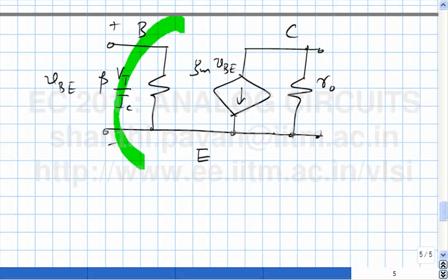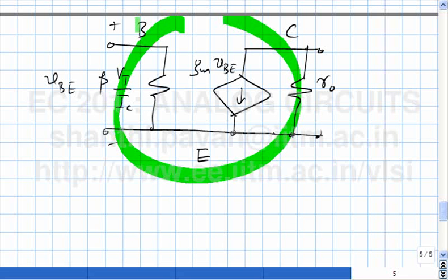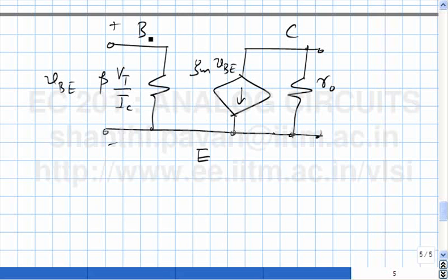The VCCS is not as ideal a VCCS as you want, because what is the input impedance of an ideal voltage controlled current source? Infinity. Here you see that it tends to infinity only when beta tends to infinity. And of course, as usual, the current source is not ideal either. There is some output impedance associated with the current source. So if I made a common emitter amplifier, for example, we see that the input impedance and the output impedance will all depend on these quantities, the beta as well as VT.